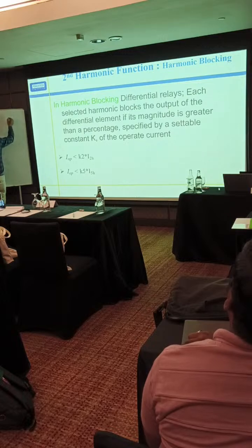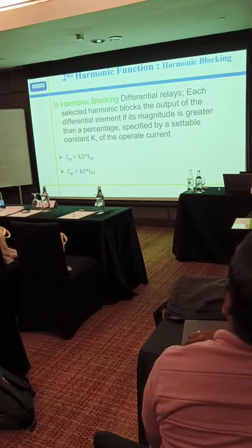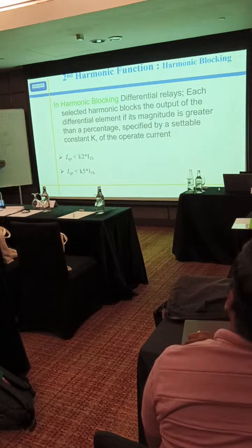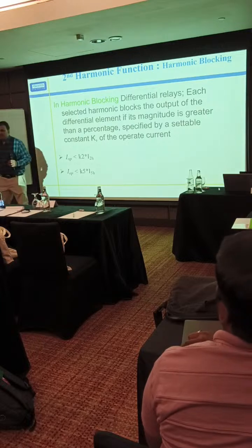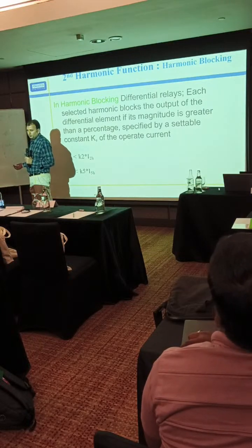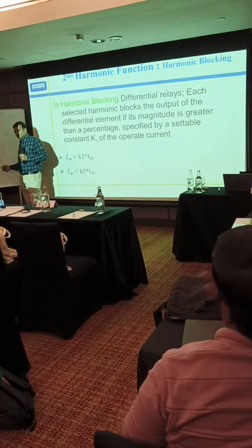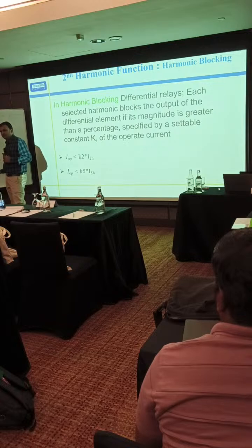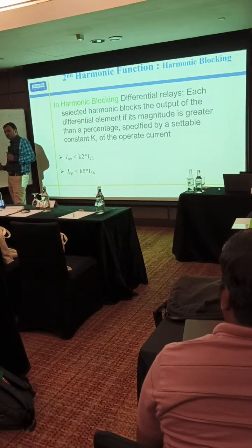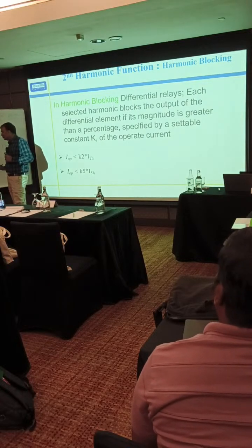So we keep it constant and reduce this. So if the setting is 0.2, then exactly at 0.19, it will trip. Sometimes 0.2 may also trip. So it will be in this range. 0.19 definitely it should trip as soon as it reduces from this.